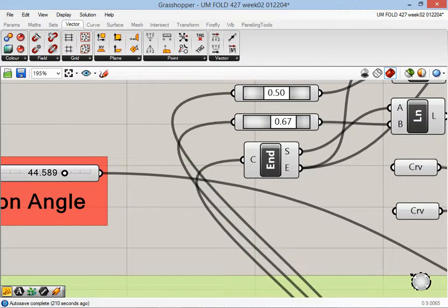Orient command. What's the difference? Just the control. A move command can only move in a vector direction. With orient, we can basically flip it, reorient it, rotate it, reorient the vector direction, so it has more capabilities. Does that make sense, guys? A move command can move something.